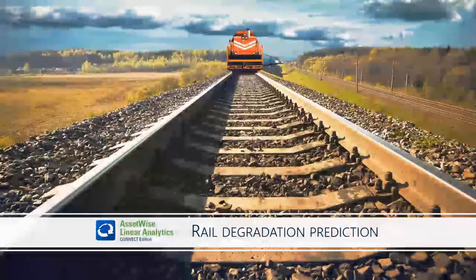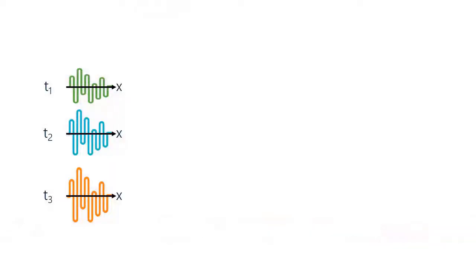Here's how AI is helping with that task. Data collected during a survey gives spatial information about the track. A number of surveys are conducted at different moments. This gives us the basis to try to predict trends in track geometry over time. Before we apply predictive analytics, though, we need to correct for two errors that could affect the machine learning results. One is correction of position misalignments, and two is removal of outliers.